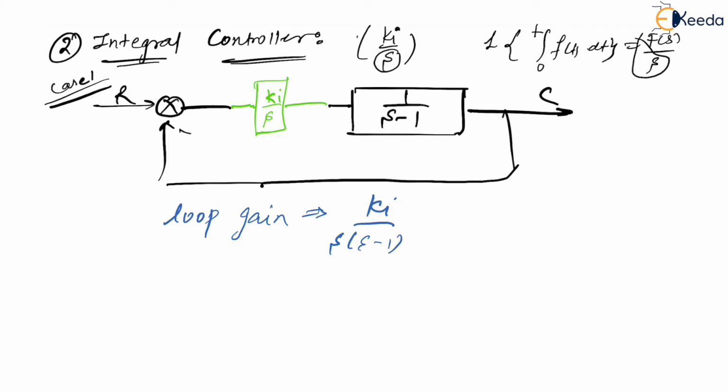What do you find now? Initially, the system was unstable. Yes, it was unstable. But now, you have added one more s. Sone pe suhaga, we say that in Hindi, right? You have added one more pole at origin. Initially the system was here, but now you have added one more pole here at origin, which means you have made it even worse, even more unstable.